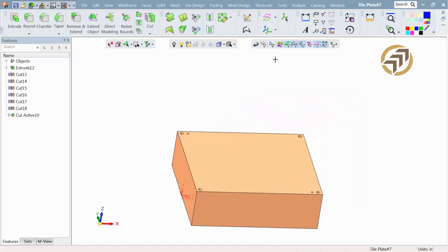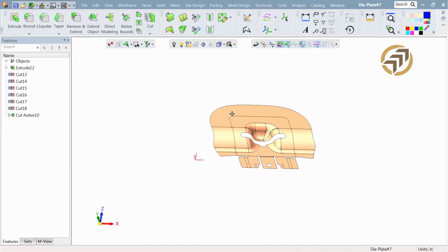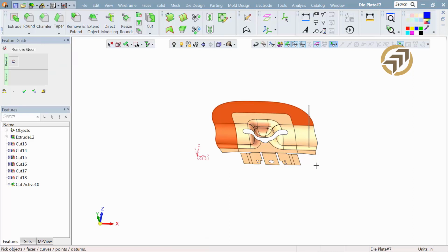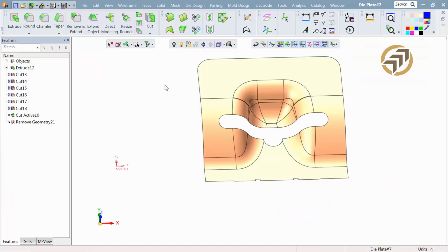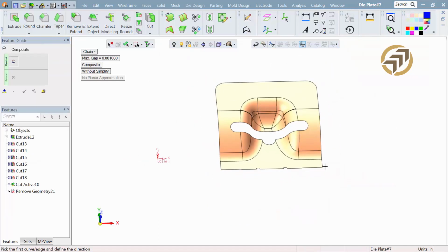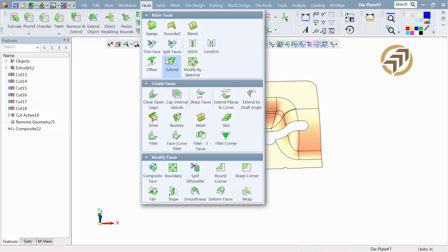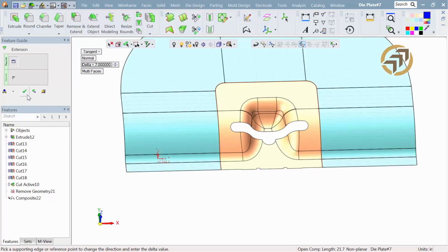Everything is still there, I'm just looking at one part. Makes it much easier to work with. Alright. Blanking off the steel, we can work with what we're going to cut it back by. Here I'm just going to simplify my shape a bit. Alright, so we don't need those faces surrounding us. And what we'll do now is extend this outer edge all the way around like you see here. So I capture that edge, use my extension tool, something plenty big enough that will get out past the outside of my block.